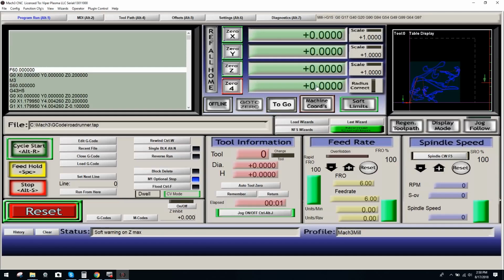If you lower her, if you bring her down, let's say 2 inches, you will be golden, and then you would home it. Okay, and you can home that once again either by zeroing it or, again, there's a couple different ways. I personally would use my auto tool touch plate. That's up to you. Most guys are using that. You can zero it out any way you like, but that is the premise. You have to have enough axis travel to use your Z.